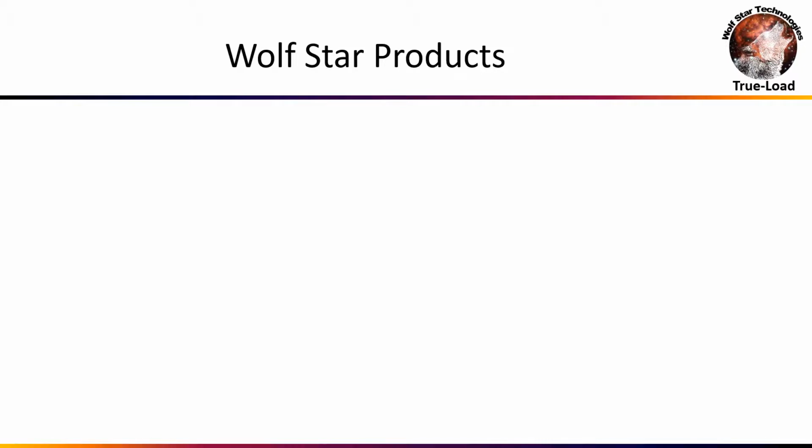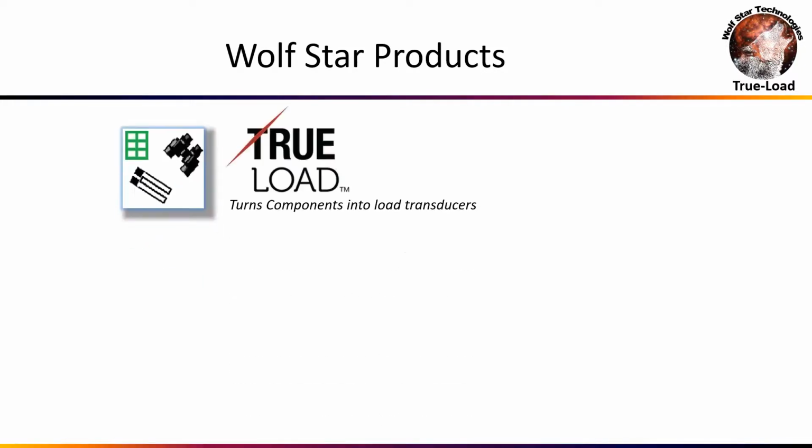So the products from Wolfstar Technologies are TrueLoad. This is our flagship product. It turns components into load transducers. What we'll do is we'll take your FEA model, we'll look at unit load cases on the FEA model and the strain responses there. We'll extract a correlation matrix that relates strain response to loads at certain locations.